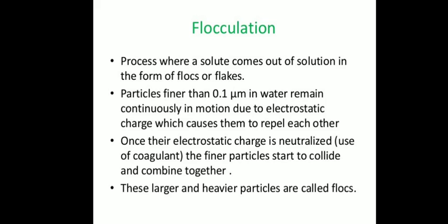Whenever finer particles of less than 0.1 micrometer size are present inside the water, due to electrostatic force they continuously keep on moving. Once these forces change or neutralize, all these smaller finer particles start colliding with each other, and a larger or heavier particle is formed, which is known as a floc.